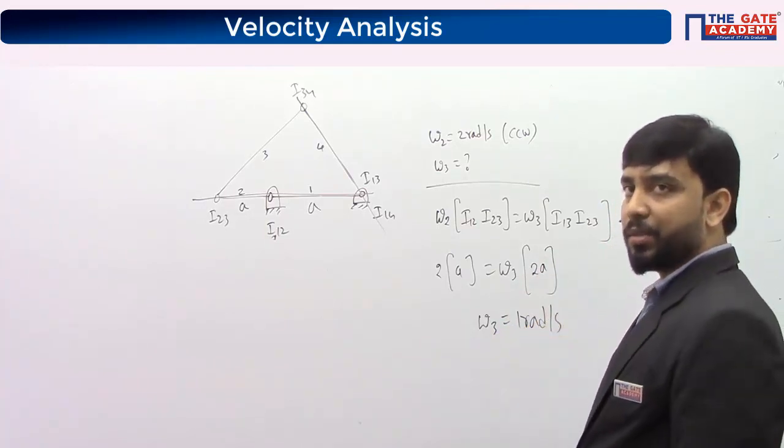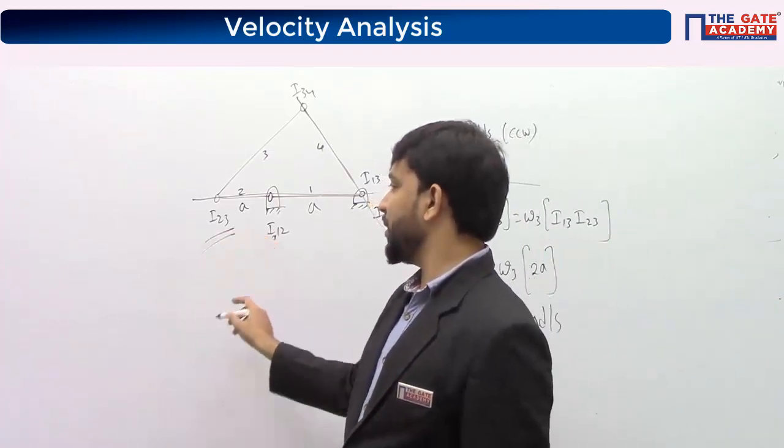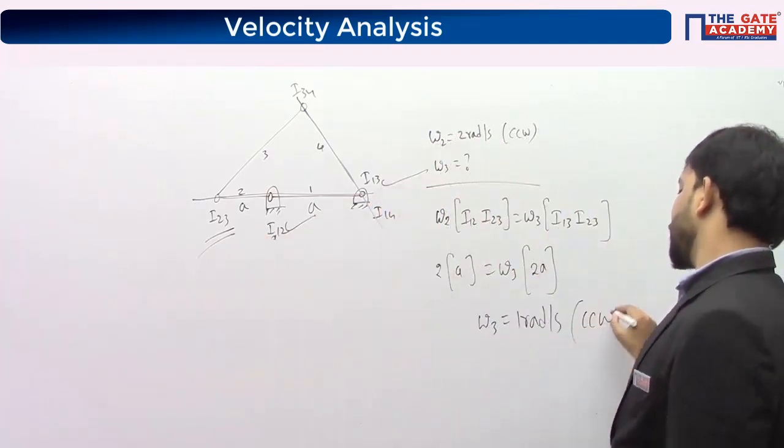What's the direction of rotation? This is the common I center for 2 and 3. This is I12, this is I13. Both are lying on the same side, so both rotate in the same direction.